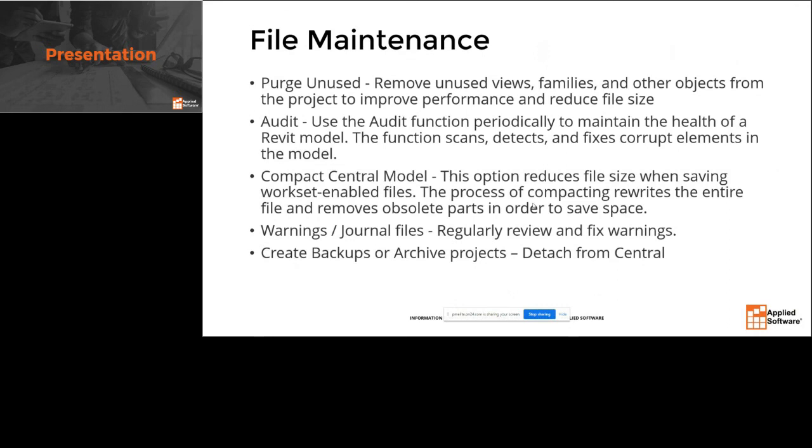And when you're trying to use those in a 2022 project, a lot of the geometry and the X data that is built into these from way back in the 2015 version no longer exists in the Revit world now, and it causes major issues, right? So that's how the families get corrupt.